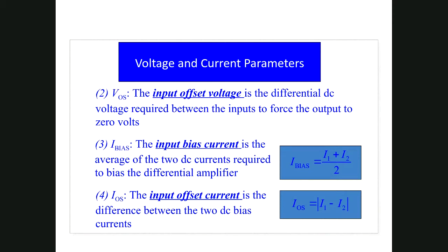If this DC voltage is there in the circuit, somewhere its effect will be there in the input, and this input, which is multiplied by a very big value in the amplifier, becomes a value in the output. So even if you are not applying any special input, because of these DC voltages, you are going to get some output.